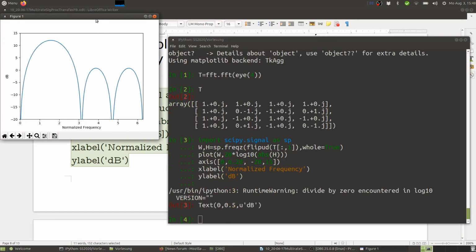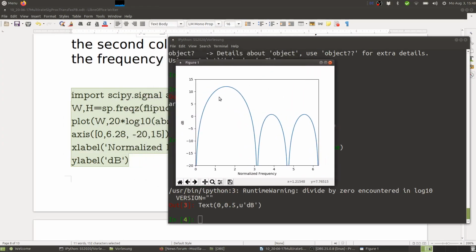Yeah, so here you go. Looks kind of funny, right? This is basically the passband of this filter. So remember, we have not the lowest one, so it's not a low pass filter, which we can also see because at frequency 0 it has a lot of attenuation. Then it has this kind of round passband. This is the passband of our subband number 1. Then here you have a transition band, and here you have the stop band.